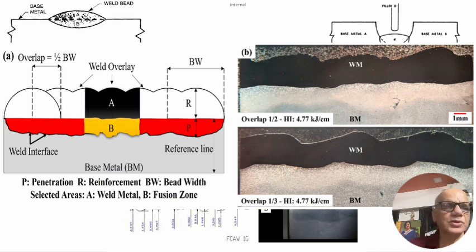parameter which I want to show here is, see this red and yellow portions, they are our penetration side, and the penetration should be as uniform as possible as shown here. Still there are few areas like this P here which is larger, here it is lesser, and this is something which will give us trouble in our bend test.